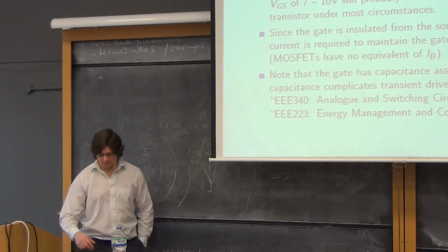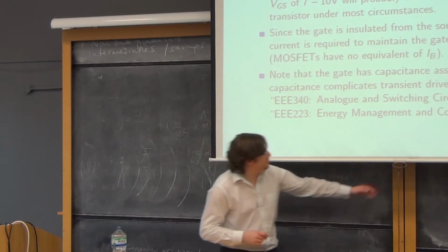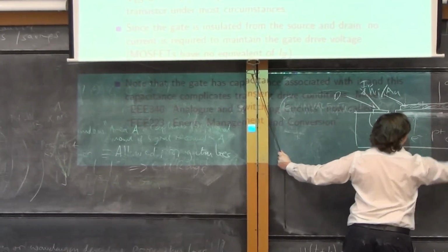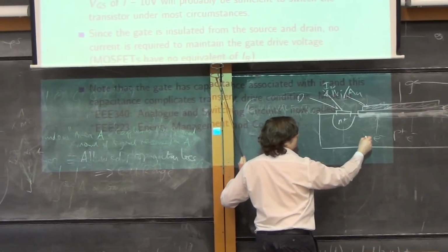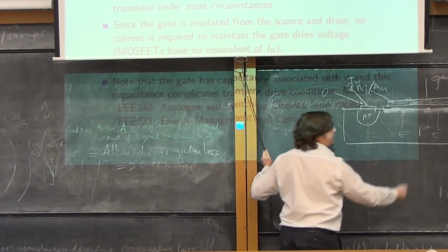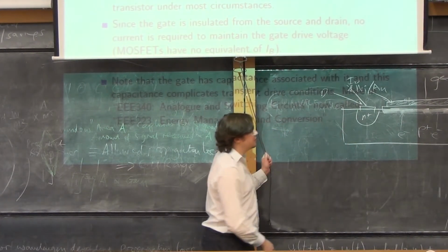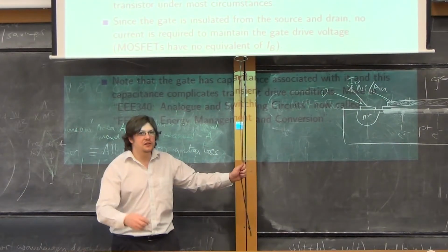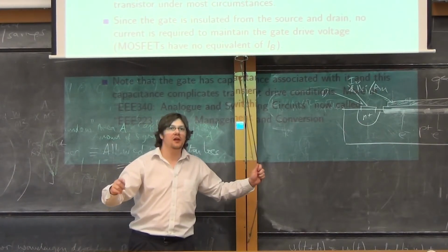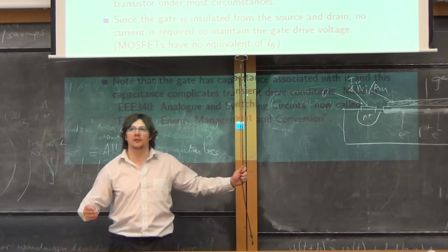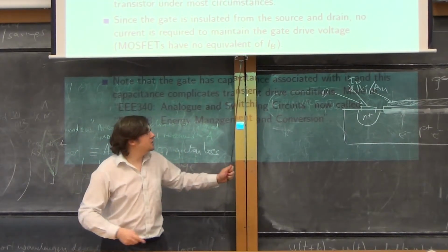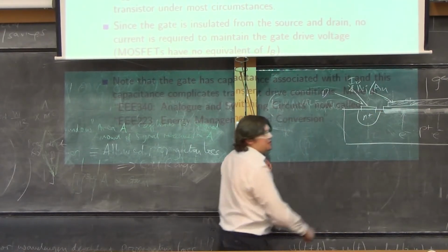Anyway, where I was getting to with that, which I never actually said specifically, is we have a large electrode here, which is made of metal, and we have a not very semi-insulating bit underneath, because this is full of free carriers. Most of them are holes, but there are some minority electrons as well. So what we've really got is something conducting, a piece of gold, something insulating, a piece of glass, and below it something which is broadly conducting. So we've got conductor, insulator, conductor, which is a capacitor. So this is how the gate capacitance comes into being.